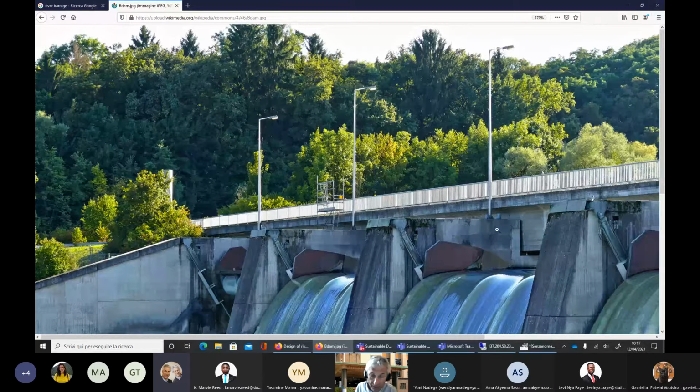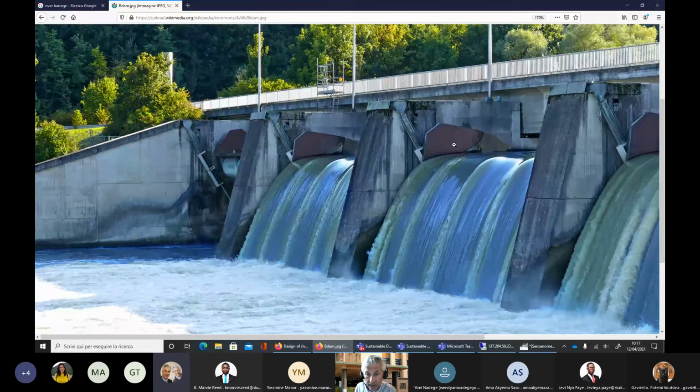We will see it in more detail. So through these mechanisms, I can lower or increase the level of the weir, the level of the threshold, which means that I can regulate the water level upstream, okay? And in fact, you see here in the extreme left, look at my mouse, the weir is closed. There is no water flowing down, okay?